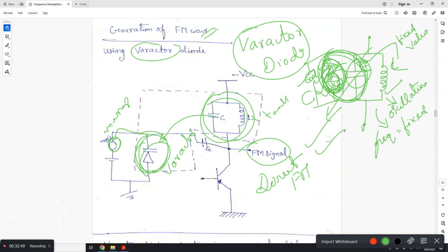You can ask me, is there any one circuit which generates FM? No. As many circuits as you have to generate an oscillator, that is how many ways you have of generating FM. Any oscillation generating circuit will be either an LC, RL or RLC circuit. If you vary one of the components in that, such as the capacitance, ultimately your frequency of oscillation will vary. So now the next circuit I will talk about.